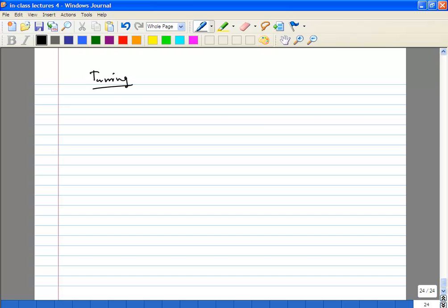Okay, so now tuning. We talked about the varactor tuning, right? Before that, you need to choose a certain K_VCO. Now, if you choose all the variable capacitance as just the varactor alone, if you have just say one huge varactor, let's say your tank capacitance was 2 picofarad. If you choose a 2 picofarad varactor, what you will get is K_VCO will be hundreds of megahertz per volt probably, if I had to take a guess.